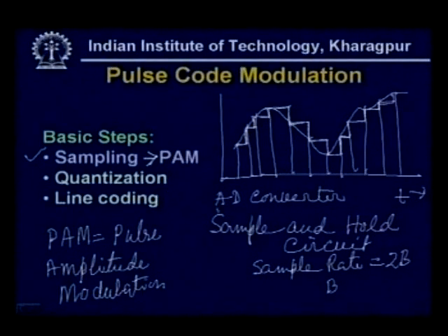If it is 8 bit, then it will have 256 different quantization levels. So, the analog value was having all possible voltage levels. It is now converted into some discrete values depending on the number of bits used in the analog to digital converter, and that leads to what is known as quantization error, as we shall discuss later. And after we have got the digital data, it can be converted into a digital signal using suitable line coding, which we have already discussed.